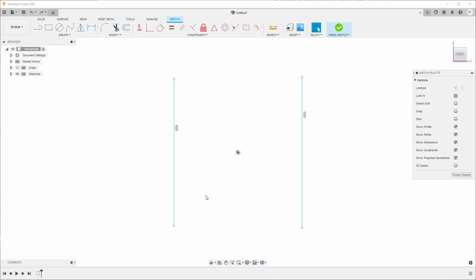Fusion 360 also has the capability to place automatic constraints to help speed up your workflow. In this example, if you draw a new line that is connected to the end of this existing line and drag away, you can see this blue perpendicular symbol where the two sketch entities meet. What you are seeing is just a preview of the automatic constraint, as you are currently still free to move this particular feature in space. It is only when you click to place the geometry with the preview visible that the constraint will be placed, as confirmed by the respective constraint symbol.